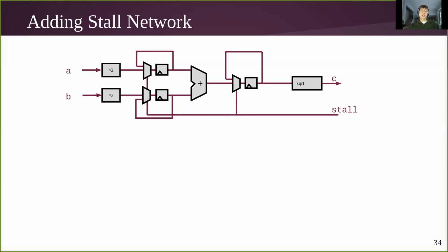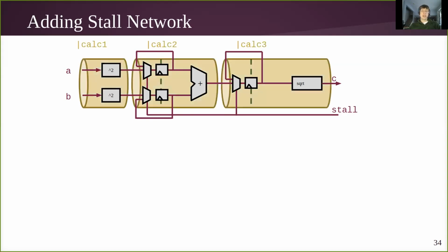So taking this logic diagram and literally translating that to transaction level Verilog, well, first depicting this in a transaction level Verilog mentality, we now have to break our pipeline because we're no longer free flowing. So we've got two recirculation points, which break our pipeline into three.